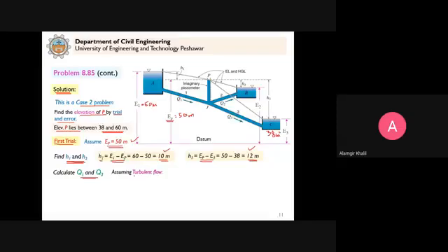That would be a trial and error within a trial and error procedure. To avoid that, we assume turbulent flow, and now we can eliminate the friction factor by using this equation directly.